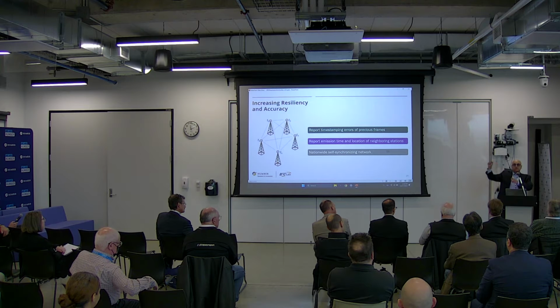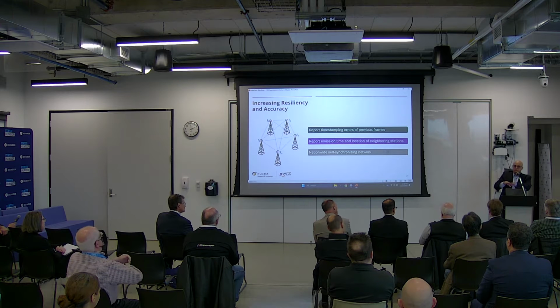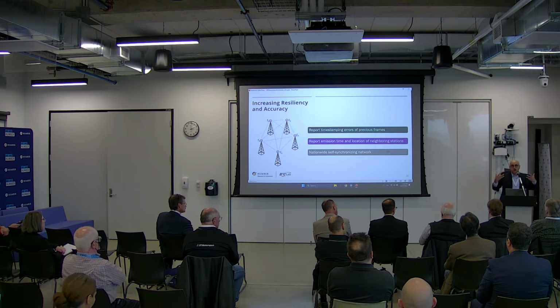For the 15 nanosecond error that we already transmitted, next time you can say, by the time I transmitted, 15 nanoseconds subtracted, that is your time, the time when you sent the previous frame. So if you're running your estimator as a clock, you could adjust and get a more accurate estimation. That is one, and it's easy to do. It's just a message structure, and we already have the errors.